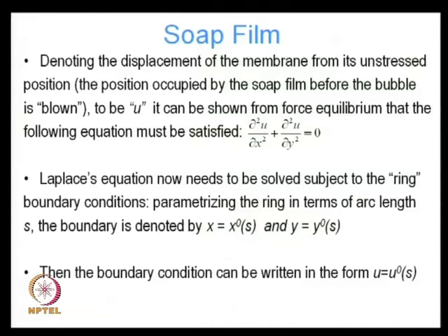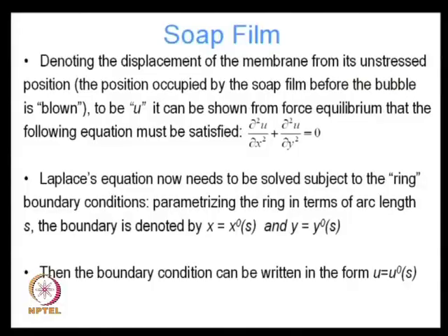So the equation, from force equilibrium, we can show that the displacement of my soap film or of my membrane must satisfy this condition, which is nothing but the Laplacian in 2D, and which is equal to 0. So Laplace's equation in 2D.